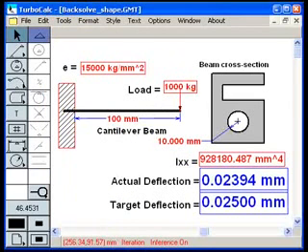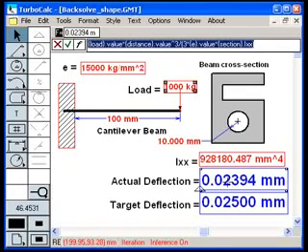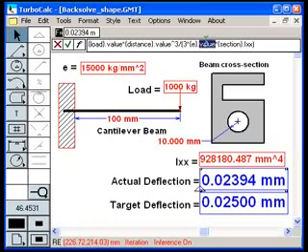And here's an example that shows how the technology is applied in real life. Here TurboCalc is set up to calculate the deflection on a cantilever beam. Notice that the beam has a non-standard cross-section. That means section properties are not available in any handbook. The beam's geometry was sketched and constrained using TurboCalc's parametric sketching tools, and the deflection calculation is being performed in TurboCalc's formula bar using the built-in functions which are communicating with the empirical value, the dimension, the empirical value, and the geometry in the worksheet.